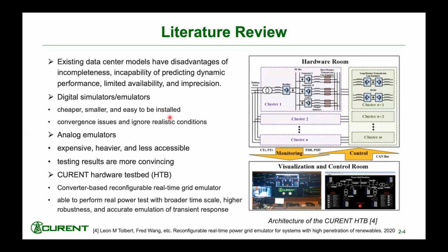On the other side, the simulation or emulation platforms include digital simulation tools like PSCAD or MATLAB Simulink, real-time digital emulators such as RTDS, or analog-based emulation platforms with downscaled prototypes or hardware testbeds. The digital-based simulators or emulators are cheaper, smaller, and easy to install.